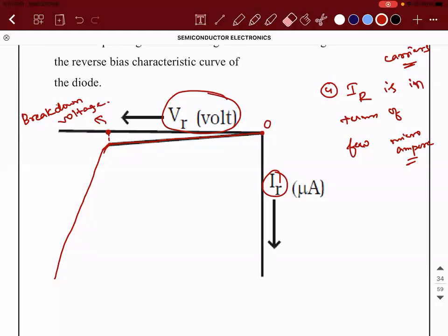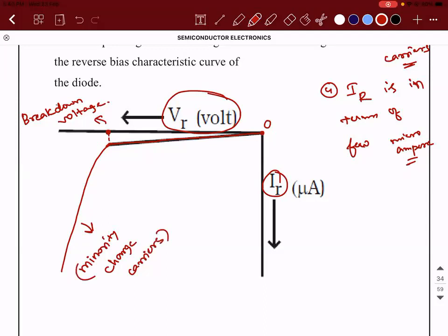In the case of a PN junction diode, we can say that the current is going to be something like this. So current will increase when there is an increase in the value of voltage also. And this current is flowing only due to the minority charge carriers. Never forget this word. It is purely happening because of the minority charge carriers. So give me a confirmation. Are you clear with what is biasing, forward bias, reverse bias, and the I-V characteristics?